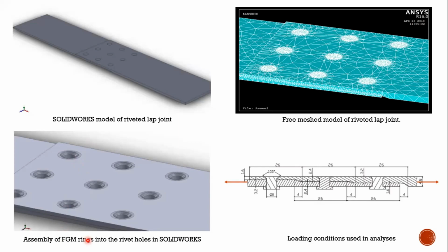then there is a huge rise in stress concentration. So we want to reduce that stress concentration. What we can do is employ some gradation in the material at that particular phase, and we can have a smooth transition of material from one material to another, and we can reduce the stress concentration. So that is the concept behind FGM.